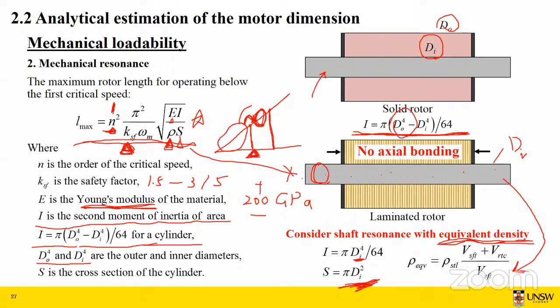But if it is beyond the critical speed, then you need to consider very carefully whether this project is doable, and if the first critical speed can't be avoided, how do we solve this problem? Normally it's either selecting a much stronger material for the shaft, stiffer and stronger, or we reduce the length of the rotor, or we make the rotor lighter. Okay, there are still ways to avoid operating beyond the first critical speed.